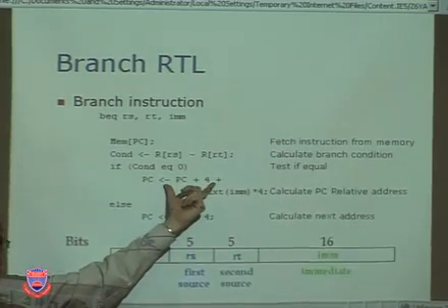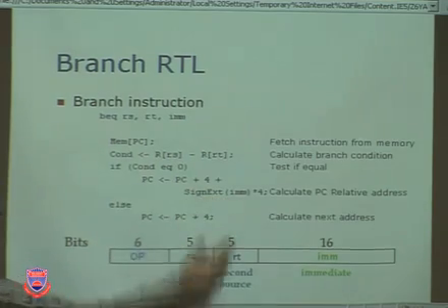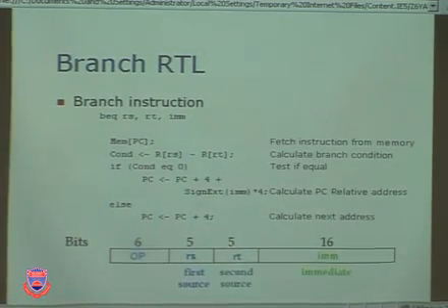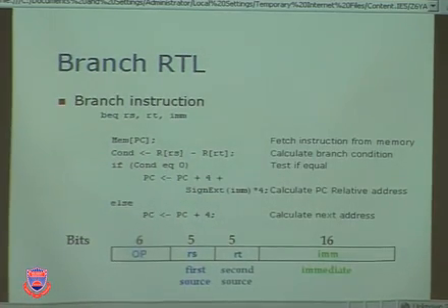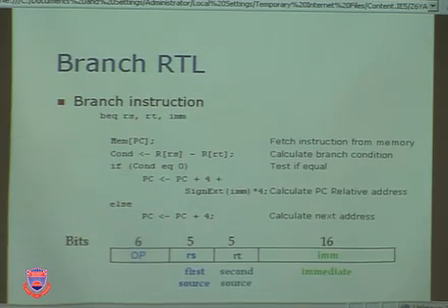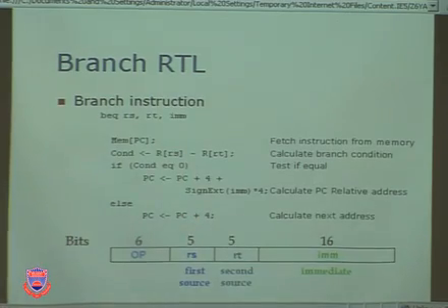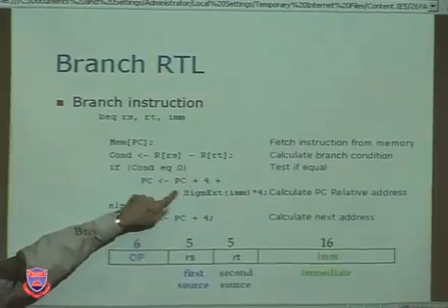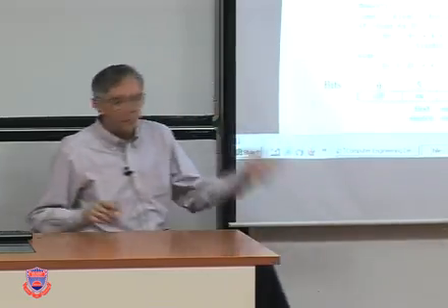So, if this is the standard model, then just add this to it, and that lets you go relatively forward or backward. So we need hardware to do that. If you want to get to 100 and you're at 20, you need to branch forward 80. Or if you're at 20 and you've already got it at 24, you need to branch forward 76 bytes. So therefore, we have to have hardware that'll change the PC not by 4, but by 76 plus 4. Got to have hardware to do that. That's what this is saying. This is what I want. Hey, where's the hardware? The old hardware I showed you is not going to do the job. So let's add some new hardware.